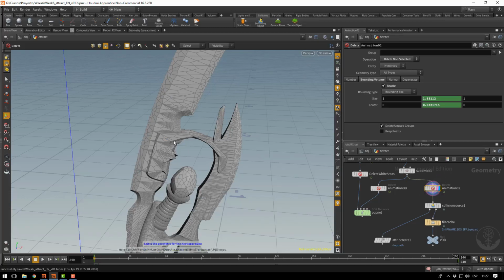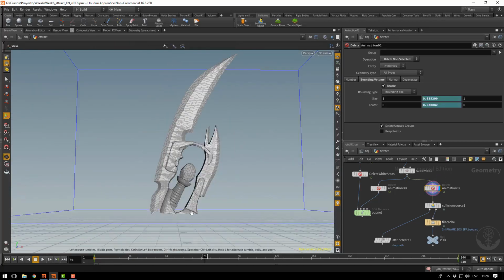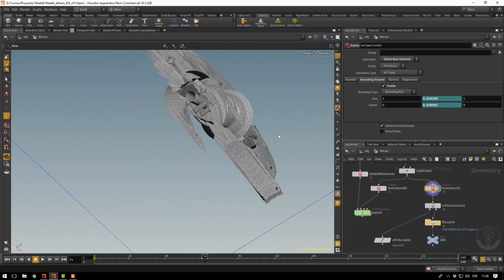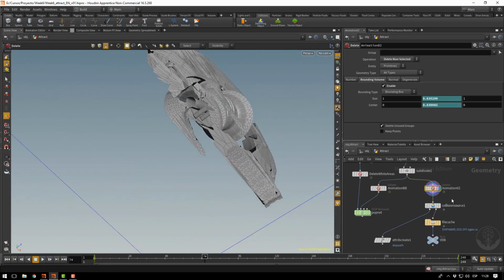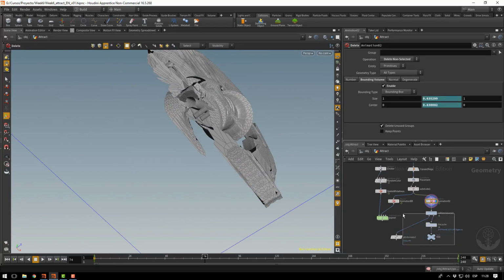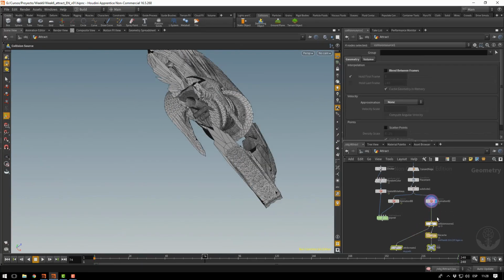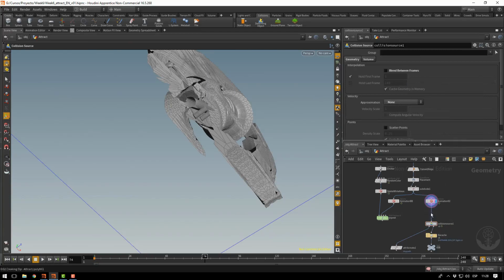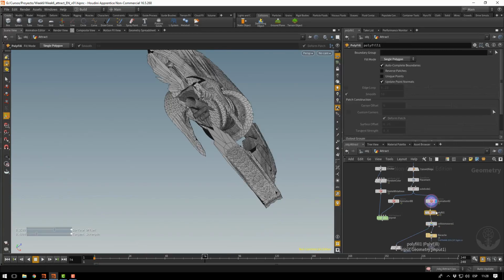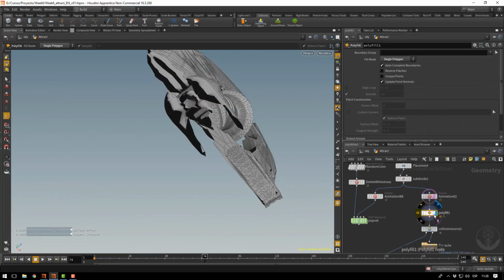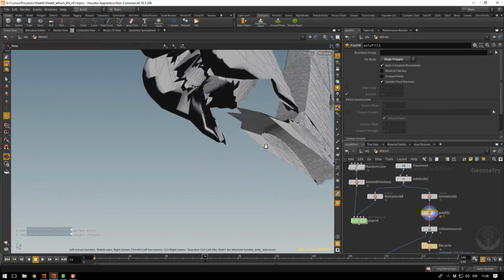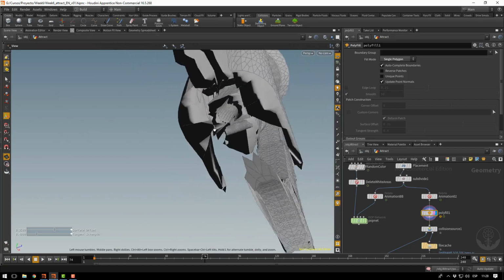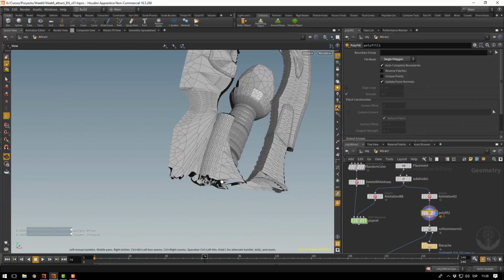So that won't happen in Houdini. So right now, if we see our surface, we see it has some holes when deleted. So the way to fix that is to add a polycap, that will add caps to our object and close it in the areas that are open.